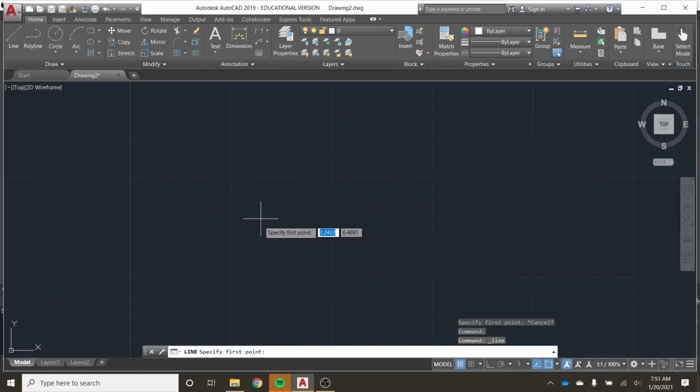We don't actually want to be operating in this mode because it makes it difficult to intersect lines and join things together if you're not in snapping to grid, which is the next function that I'm going to tell you about. So down here in the lower center to right, there is a little section of dots, and that is our snap to grid icon. If you notice, there's also a quick key for that, that's F9, so you can feel free to use that as well. But I'm just going to go ahead and click on that.